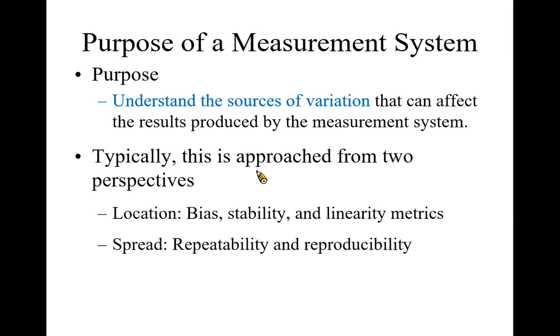Typically, it is an approach from two perspectives. The first one is location. The second one is spread. If we want to know accuracy, that is location, so we have to check the bias, stability, and linearity.